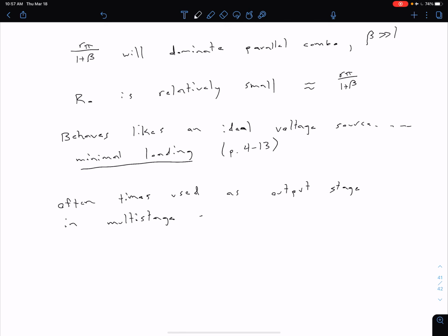We're going to come back and talk about multi-stage amplifiers really briefly in a few videos from here. But the basic idea is the same as we've talked about generally before. If we have multiple blocks and we're cascading different amplifiers, this common collector, or emitter follower, is a good output stage because it has a low output resistance. Why is that important? Because it means our output voltage isn't going to vary as we have different loads, based on our loading effects arguments that we considered previously.